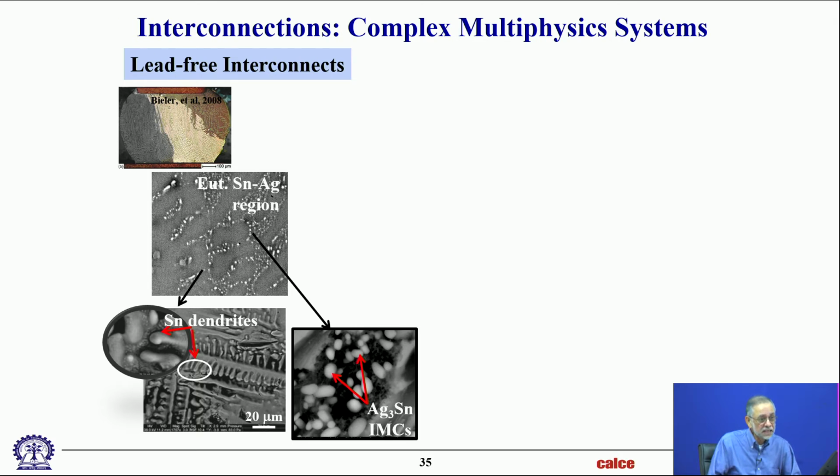And some of these tests take long. Cyclic fatigue tests take weeks and weeks. Creep tests take days, okay? Because it creeps very slowly. I'm showing it like this, but in reality you can barely see it. I have to run the test for days and days, sometimes weeks and months, at low stress levels to really understand or quantify creep behavior. And why do we need that? Because those are the models that go into my design tools to find out how much deformation I'm going to get under field conditions. Okay?